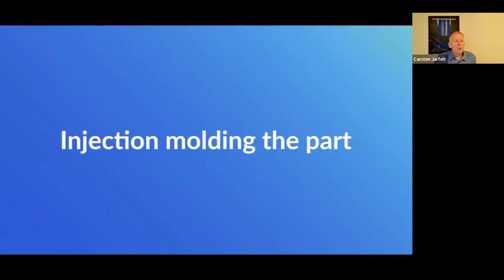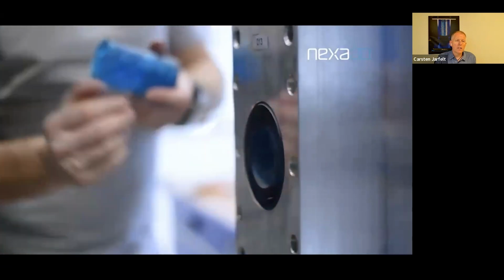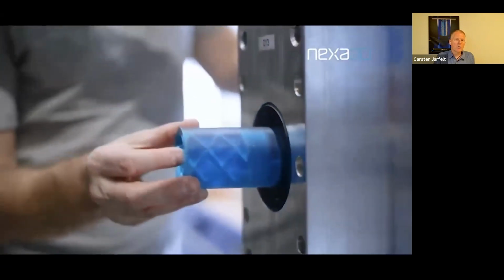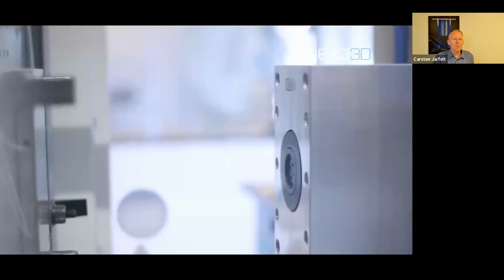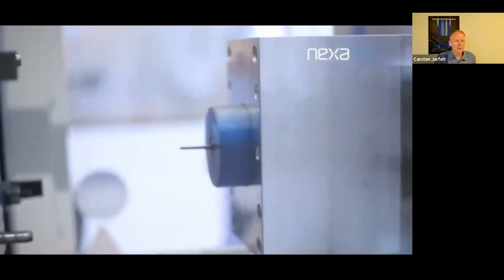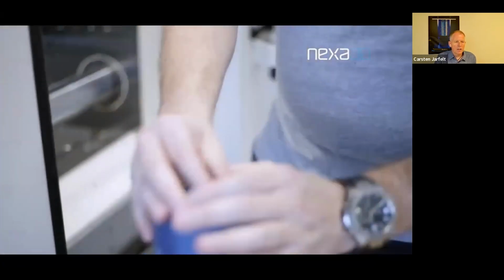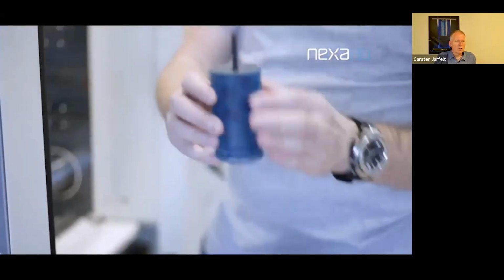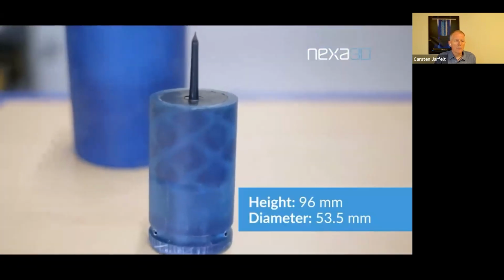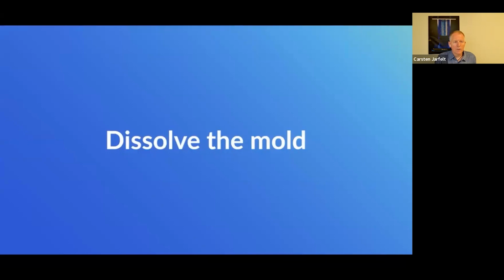And they can then be moved into an ordinary molding space. Here you see our molder putting a sleeve around a printed tool that is a little bit smaller than the mold base we have on the machine. And that is simply just to save mold bases. The spacers act just as an adapter, you could say. It has nothing to do with the molding process as such, it just holds a smaller cavity on a large machine. That was a 50-ton Krauss Maffei, by the way.